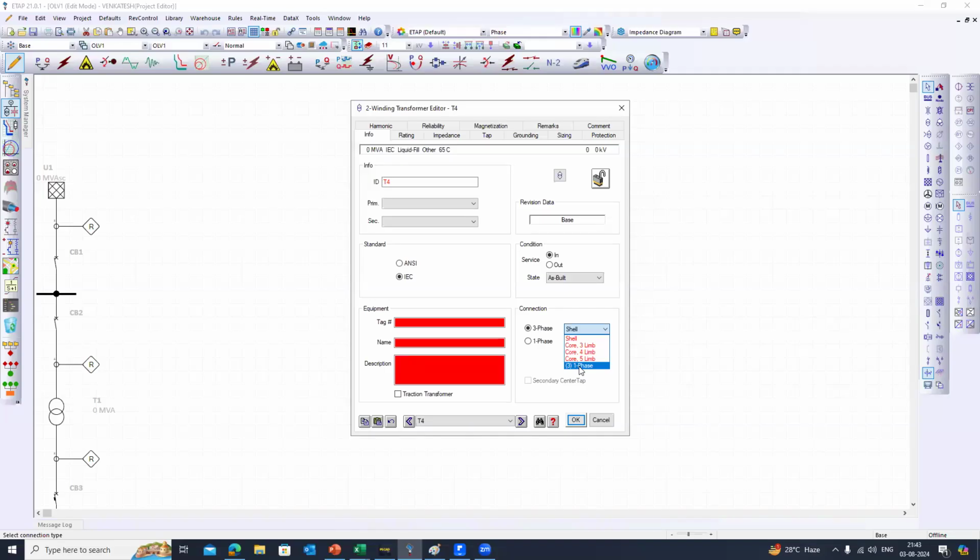We generally classify this as step up or step down, but it's not really true. It's bidirectional, right? And here you have three-phase transformers versus single-phase transformers. It depends on the number of phases, and probably you might be aware of traction transformers, which are connected with two phases on the HV winding, whereas the LV winding is phase and neutral. That is also another type of transformer.